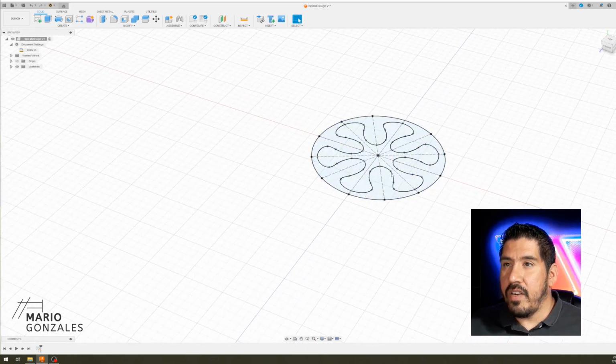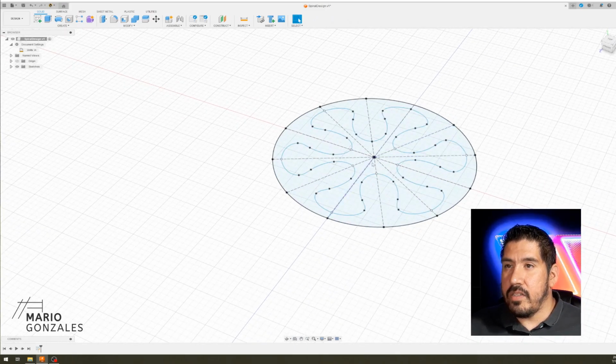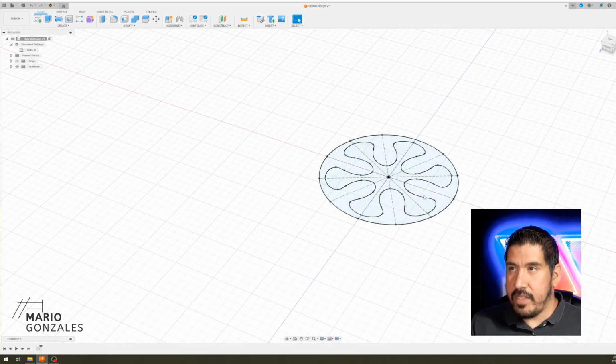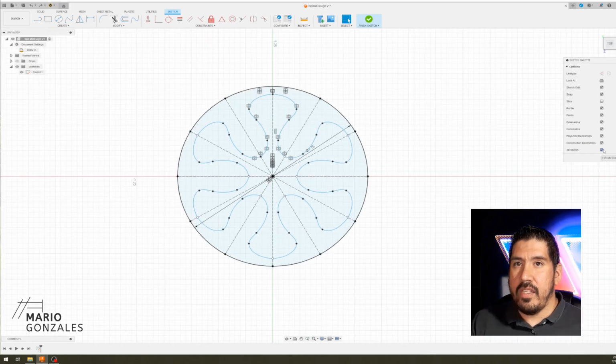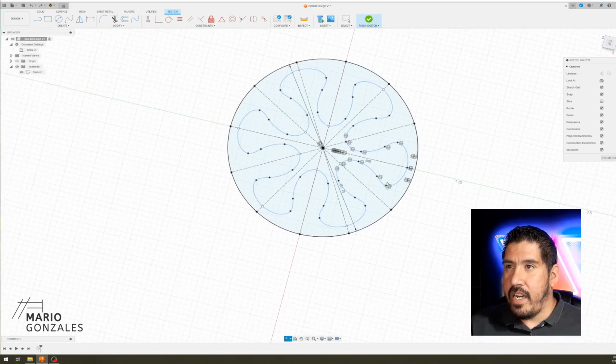And what I forgot to do is let's go back into our sketch. So I'm going to press Control Z. You can also go under Sketches, right click and edit sketch. I want to make this a 3D sketch. So you see this check mark is already checked. I'm actually going to rotate it. I'm going to make another line.